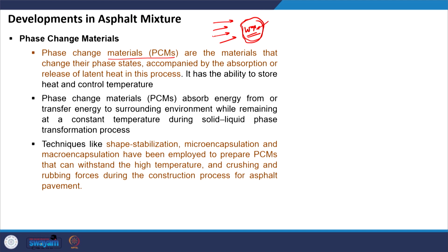Since it is absorbing all the external heat, it does not allow the temperature of the surrounding to increase, which means the heat which is externally coming is being absorbed by the wax and it keeps the heat stored within it. As the temperature lowers, it will again start emitting the heat to the surrounding and it will again solidify, depending on the transition temperature range.